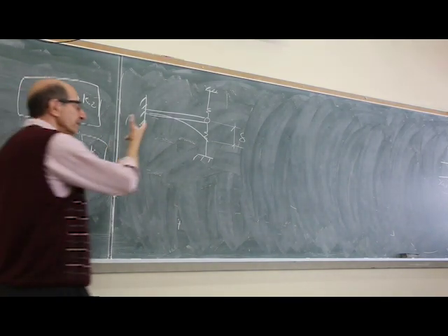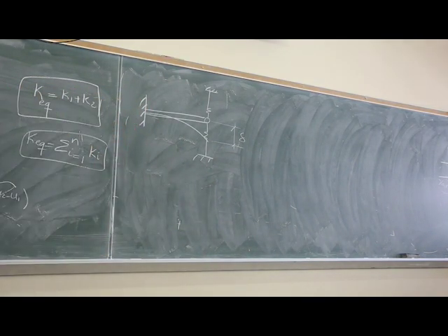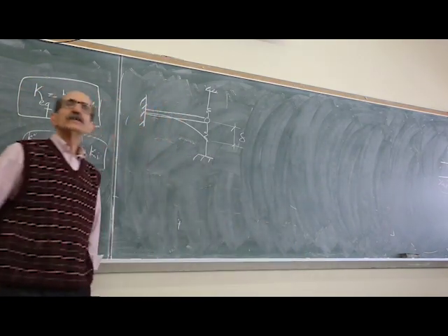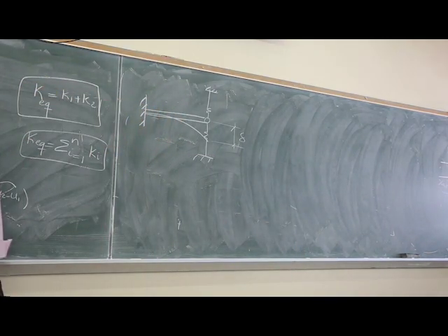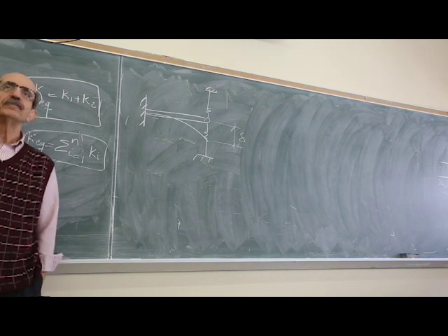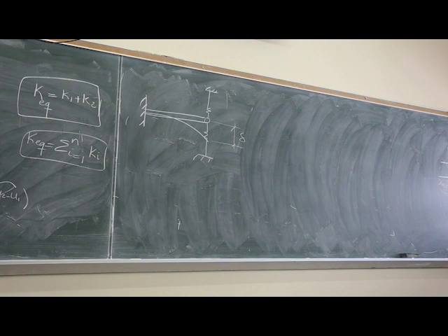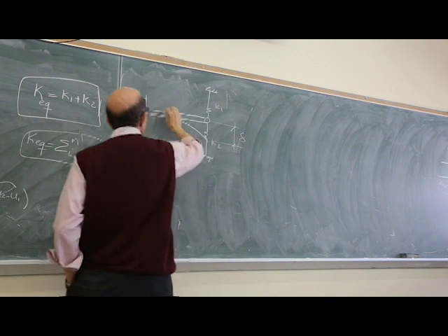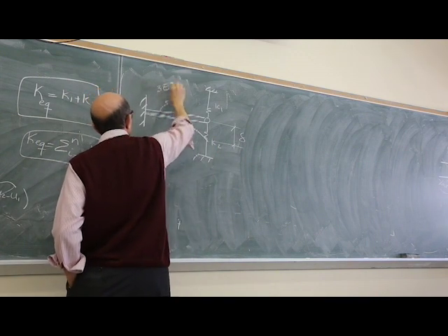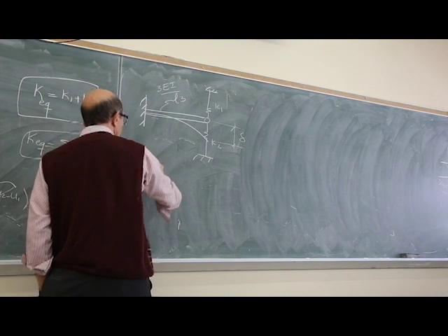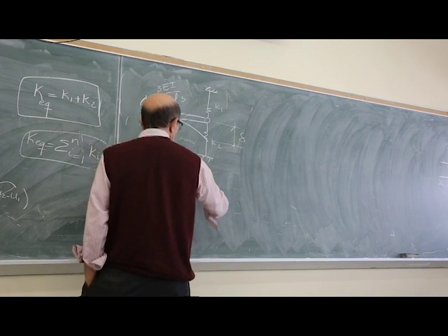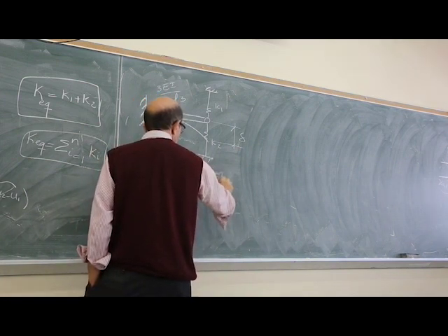So it's not the geometric configuration, but it is the understanding of whether the mass is supported by whatever number of stiffnesses, and if those stiffnesses experience the same deformation or the same displacement. If they're experiencing the same displacement, so if this is K1, this is K2, and this is, of course, 3EI over L cubed, then the total stiffness would be K1 plus K2 plus 3EI over L cubed.